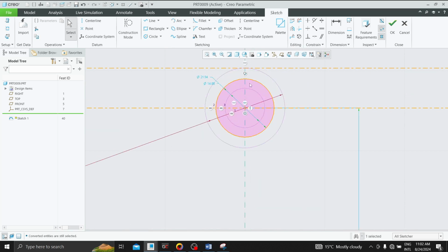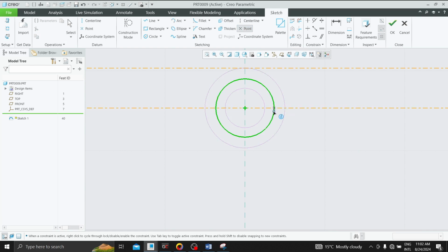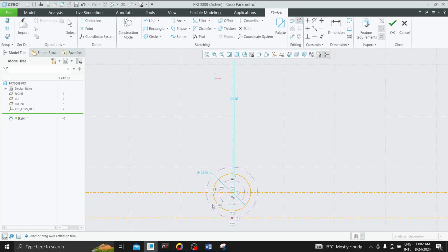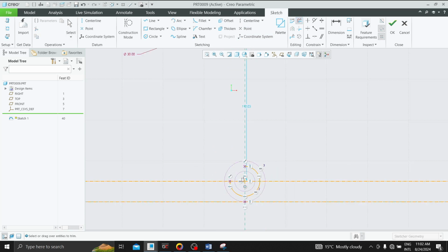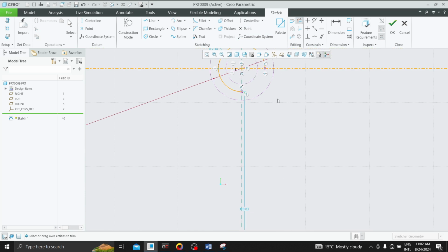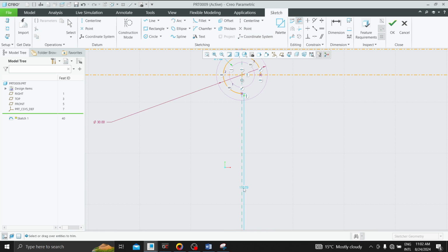Then I need to put a point on this point as well, because I want to trim that side to present that section of the spring as well. Another point here, and trim this one here, so that they alternate. And the free length is this distance now. This is the body length. That's the distance. For now, supposed to be 50.